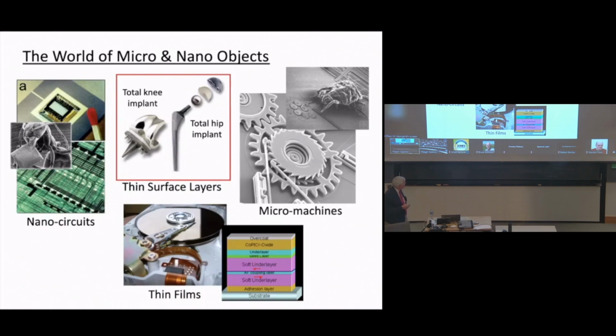So over the years, overcoats have been developed, extremely hard things. They're very much like diamond. They're called diamond-like coatings. These things are about 5 nanometers thick, and they're extremely hard, and they very effectively protect the underlying layers, and for that reason are important in this technology.